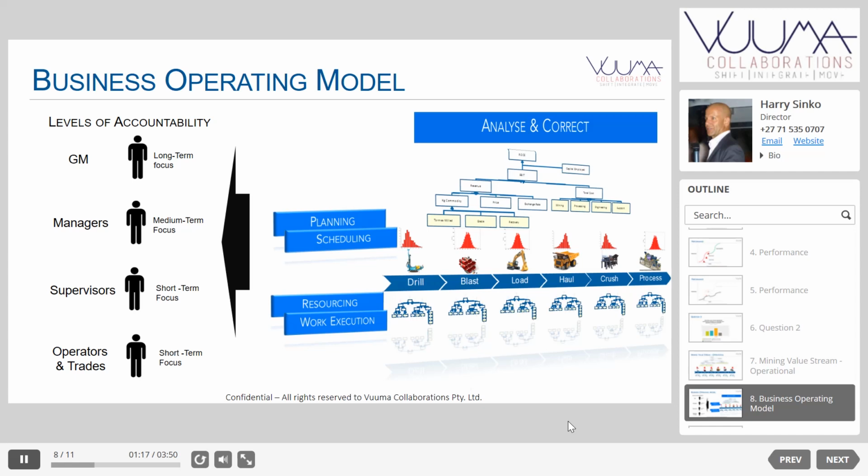Two is a duty cycle type of system where you look at how many times it does something or how long it's travelled, and then based on a certain set point, you go and replace it or do some maintenance to it. Three is a fixed time basis. Do it every 3 months, do it every 6 months, whatever it is. And the fourth one, which is usually the more sophisticated, condition-based monitored, right? So we're going to watch it, measure it. When it hits a certain point, we're going to replace it.